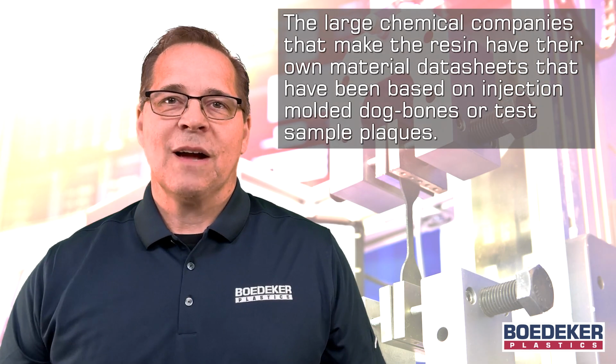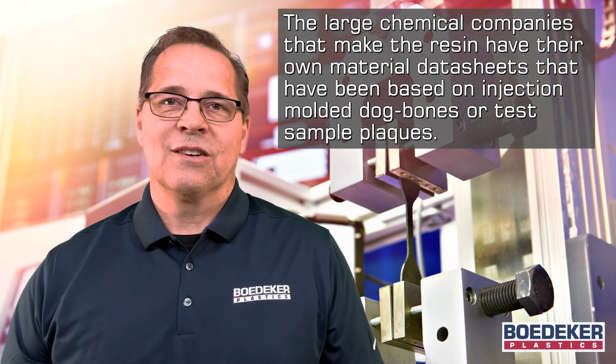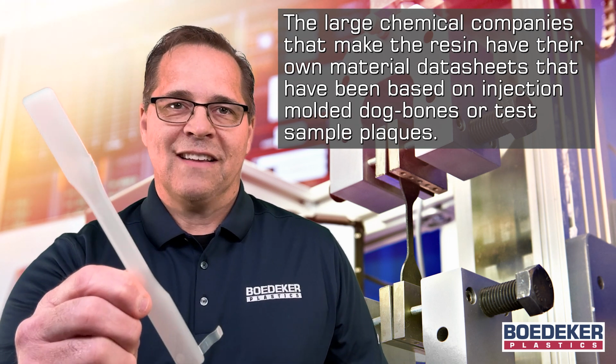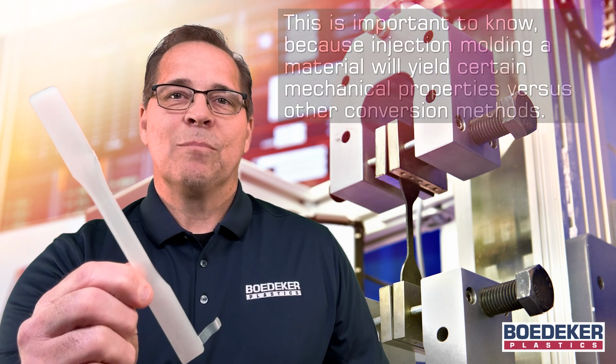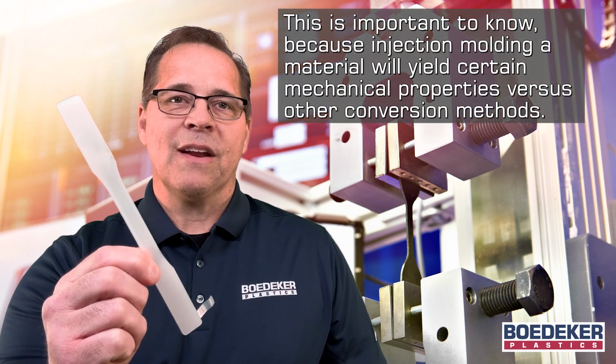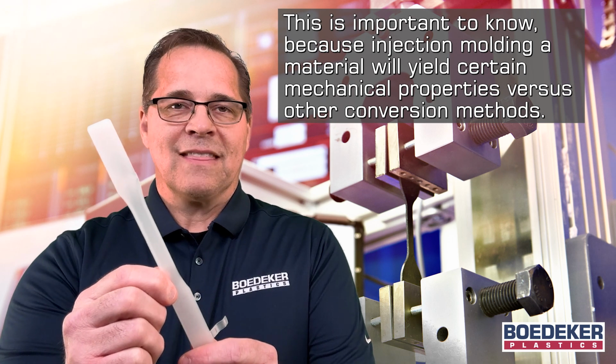The large chemical companies that make the resin have their own material data sheets that have been based on injection molded dog bones or test sample plaques. This is important to know because injection molding a material will yield certain mechanical properties versus other conversion methods.